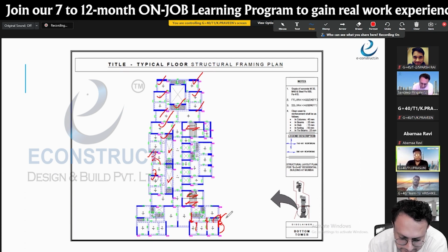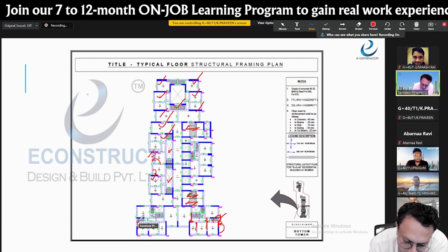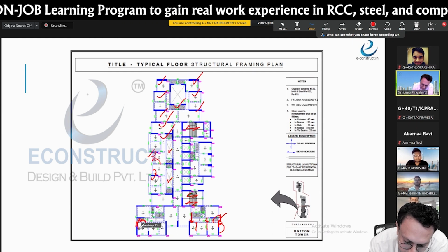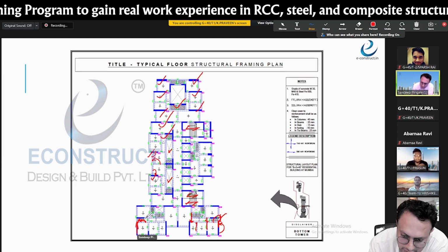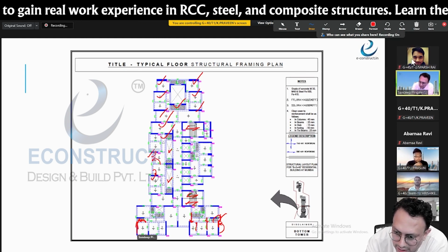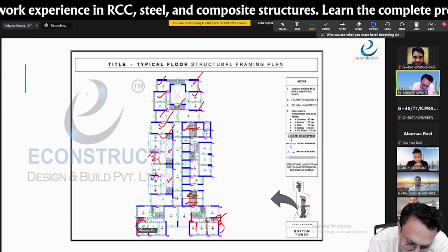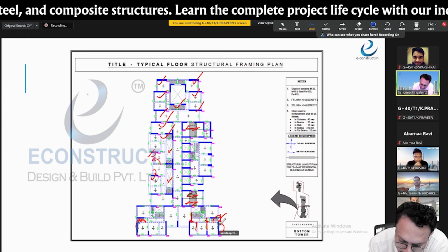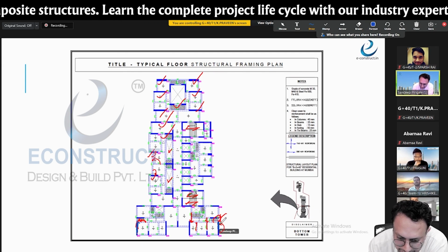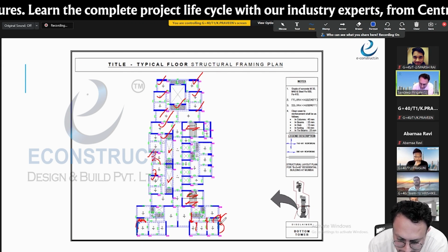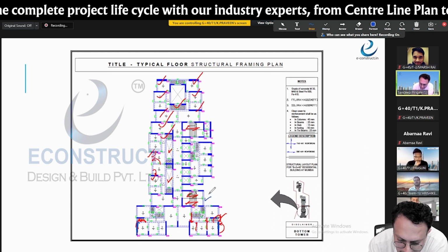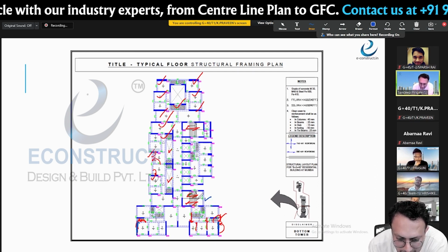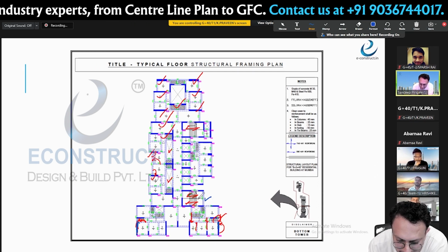Okay. Same thing here. This shear wall also can be extended so that the bearing of this beam should be transferred to the wall. I will use the same color which you are using. So shear wall will be till the edge of this. Both the cases, similar cases. See here also it is given properly. And yeah, the framing layout which somebody has done, this is so nice.